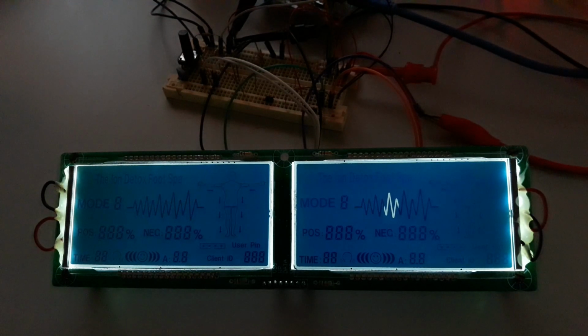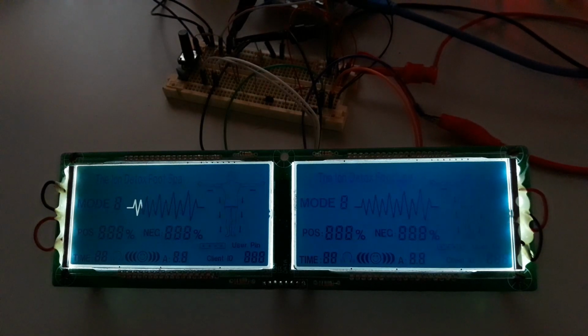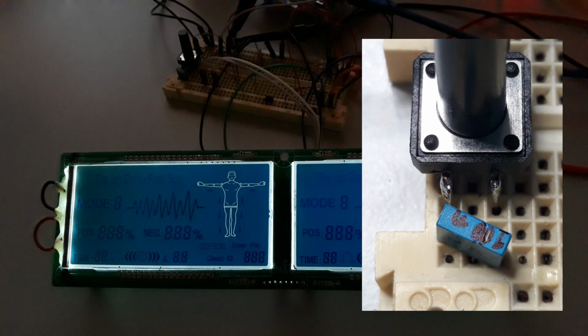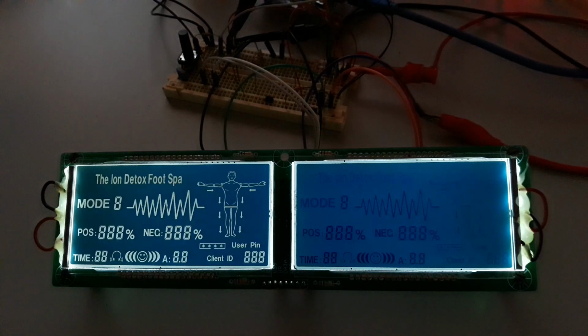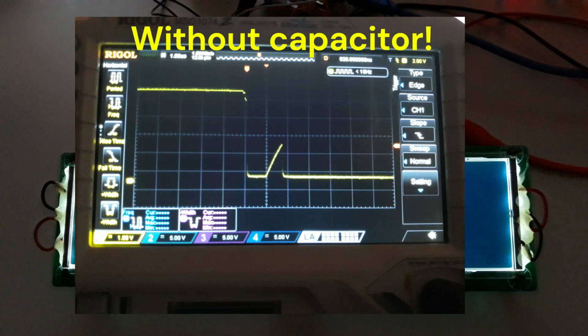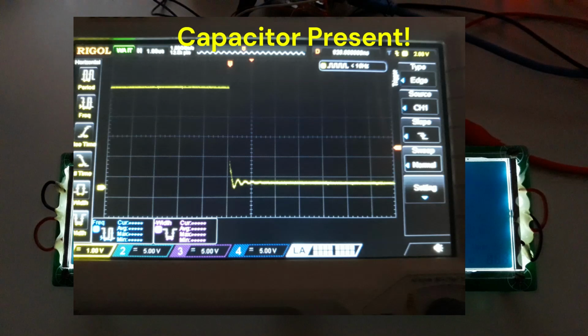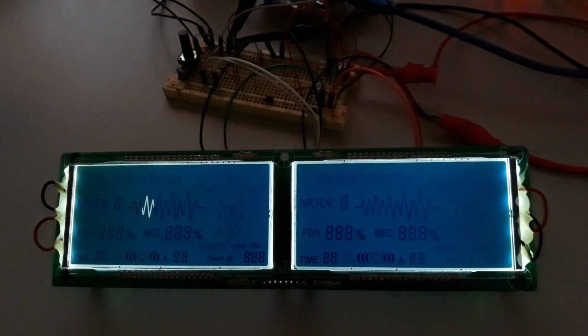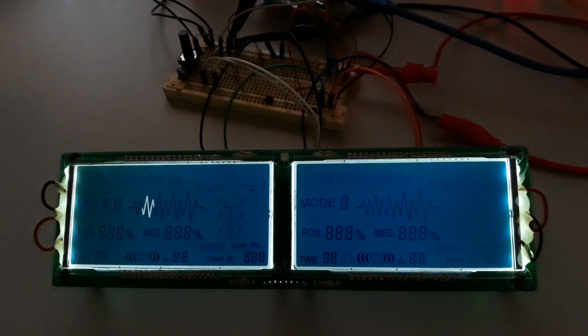Remember the importance of applying a capacitor of near 100 nano between the push button pins to avoid the bounce, which is a point that presents many complaints because it results in constant jumps. Also, you need to activate the pin mode as input with a pull-up or apply an external pull-up of 10K, for example.